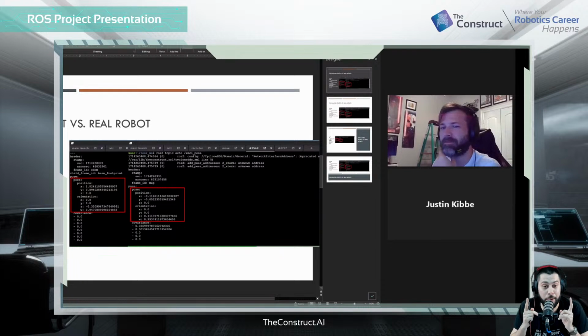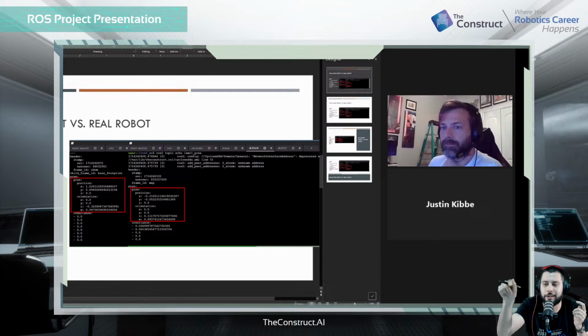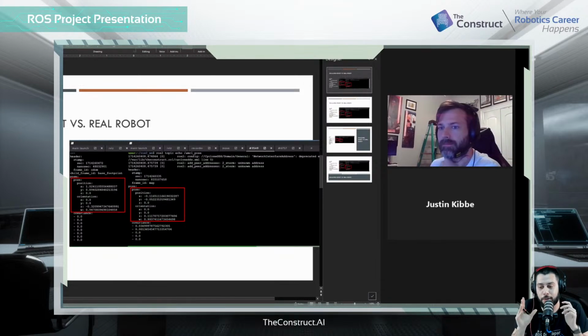It is a very good point, because my first thought also is just to look at the odometry. But basically, you're using the AMCL pose, or people also use the initial pose, the one you click. They subscribe to that, and it's like I want to go here, but it's always going to be with respect to that origin where you start mapping. And again, you can move it wherever you want. Let's say, for example, when I set up nav, I like to put it in a place where everything's going to be positive, so 1 meter, 2 meters up, and that way I can kind of see it in my head.